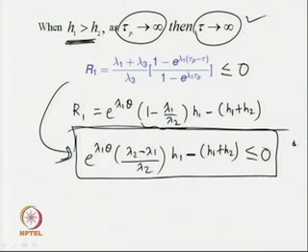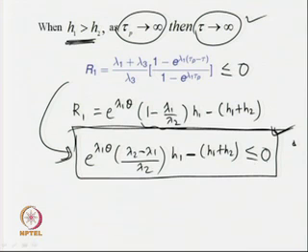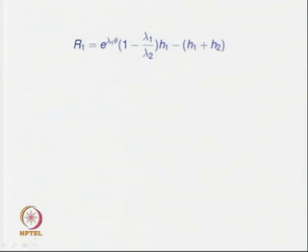further simplification of this expression will give you a condition that has to be made to obtain stable limit cycle output for second order systems particularly, and which analysis can be extended further to obtain conditions for obtaining stable limit cycle output for open loop unstable systems. Okay. So, this is the condition we have obtained. Now, we shall write that condition finally in that form.